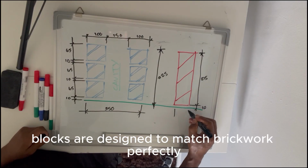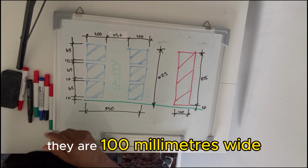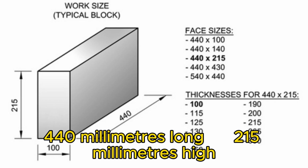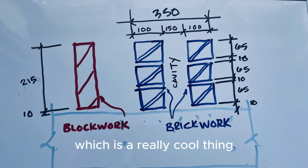Blocks are designed to match brickwork perfectly. They are 100mm wide, 440mm long, and 215mm high. So when you add the joints, they coordinate and correspond exactly with the brickwork, which is a really cool thing.